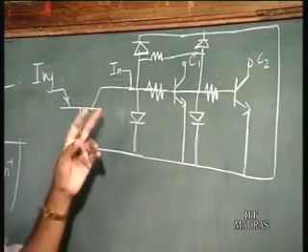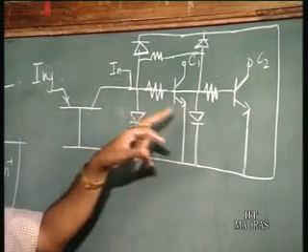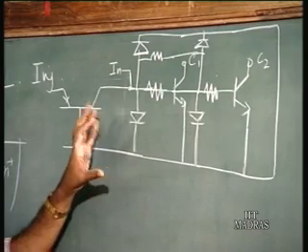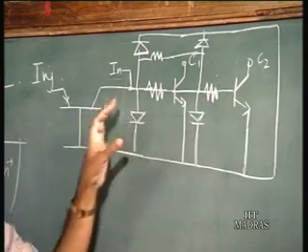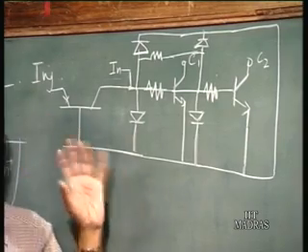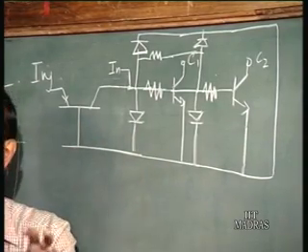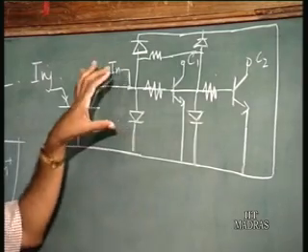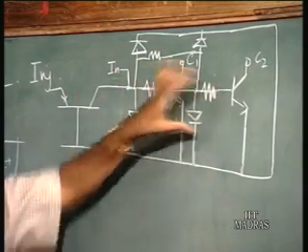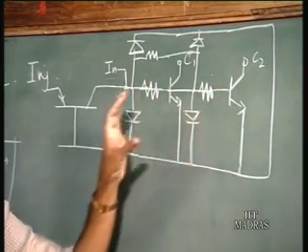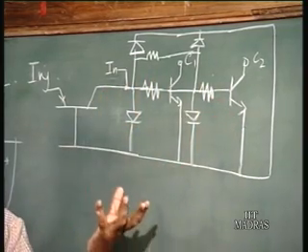Now you see that because of these lot of parasitic elements, there is going to be a lot of dissimilarity between this device and this device. Normally, even when we have obtained the condition for the proper operation of the I squared L cell, we assumed that when we have a multi-collector transistor, there are so many transistors in parallel, and all the transistors are similar.